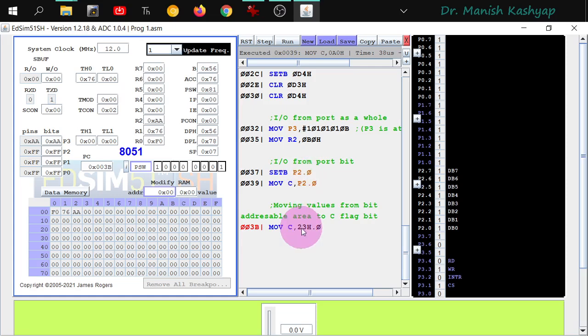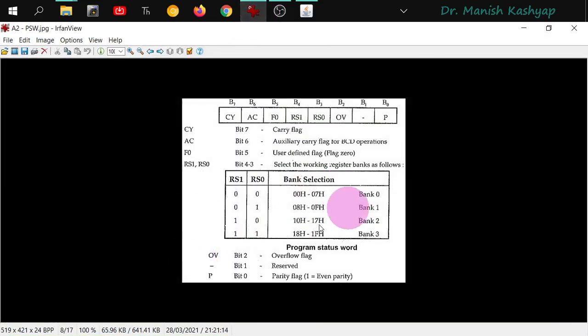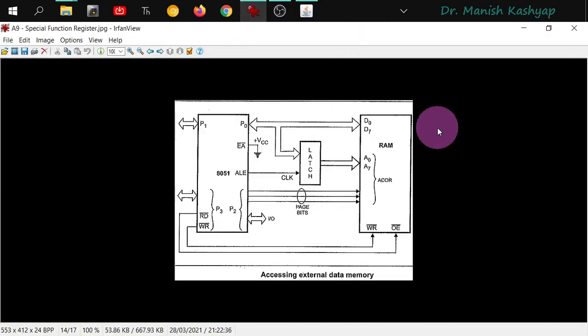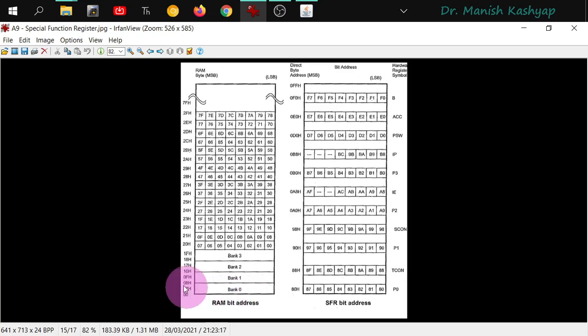This is for the port. Now, this is also very important. Let us see what is 23h.0. So, in this diagram, in this table, where is this 23? So this is 23, and dot 0 will mean this particular location. This is 23, this is 0. So this will mean this 18th address. So whatever is the value of the bit here, it will be used, right?